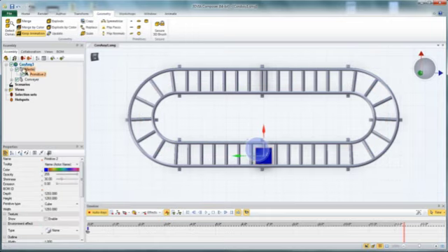So I'm going to take this out of assembly mode, just select the primitive, and then we'll go up to 2 seconds again, and we can start rotating this. Actually, right here we want to hold it, so we set a location key, and then at 3 seconds we want to have that rotate minus 90 degrees, so it animates up and starts to rotate around that curve. A couple of ways we can do that.